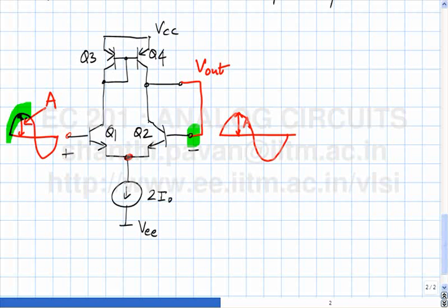Please note that it cannot be Q3. Why? The collector and the base are always shorted, so it's always sitting at the edge and nothing changes. Similarly, the same thing for Q2. Q2 and Q3 are happy campers. Which do you think are problematic? Which transistors are most likely to screw you up?